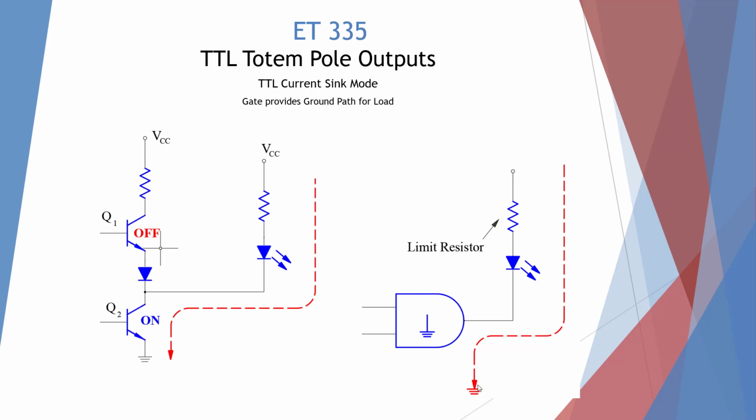Okay, so when our gate is low, we have a path to ground. If we have a load on this, like an LED, it is going to light. So our LED should point to the device when we want sink mode, and we should provide a voltage. When we're doing sourcing mode, we should have the opposite. We should have the LED pointing towards ground.